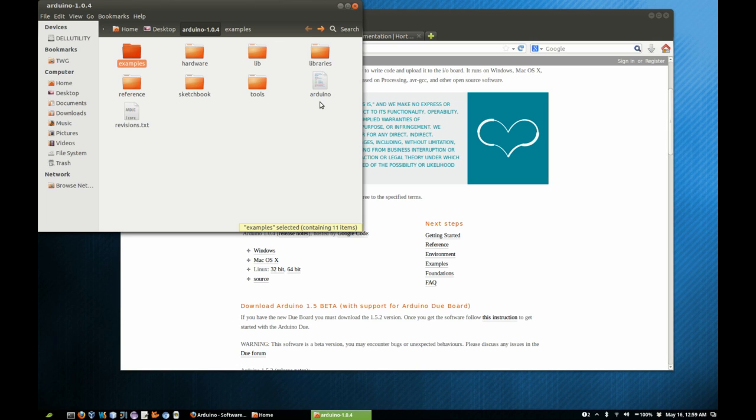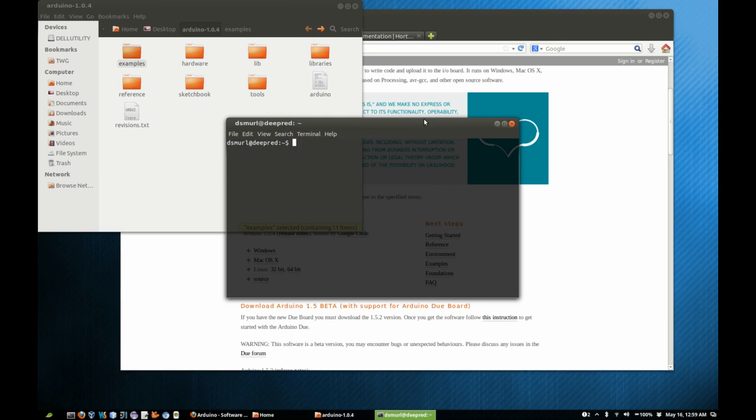I don't know exactly why this is or what all goes on with it, but in Linux, and there's probably something similar in Windows, you have to add your username to a group called dialout in order to give programs that you run as your user access to USB resources in the way that the Arduino is going to need in order to talk to this IDE.